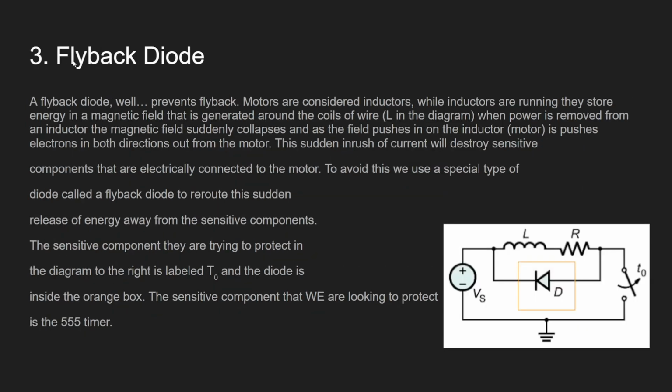The reason I needed to give that was the third item is a flyback diode. A flyback diode prevents flyback. Motors are considered inductors. While inductors are running, they store energy in a magnetic field that is generated around the coils of wire.